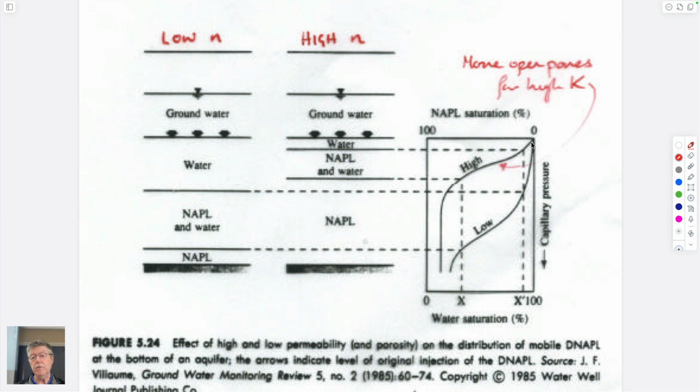This one would be one where the non-aqueous phase liquid goes in at a very low bubbling pressure. And once it goes in, all the pores are the same size, so it completely saturates those. So this would be kind of a high porosity and high saturation in the system. And this high porosity would be arranged in terms of this capillary pressure versus saturation curve with depth.